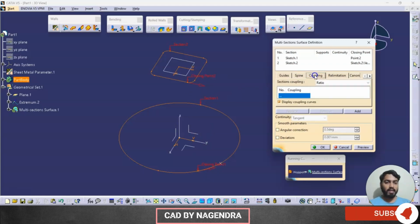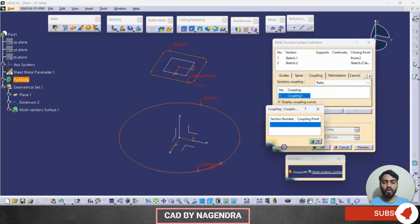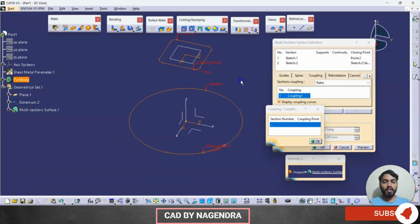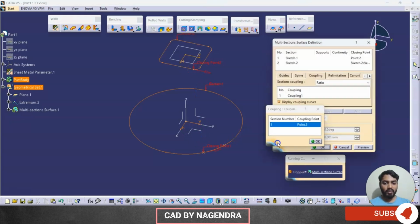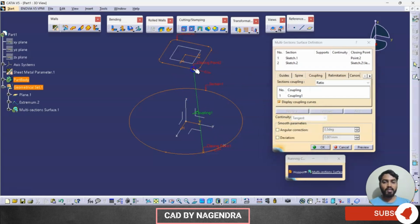Then we'll go here with coupling, add. To create a coupling we need 2 endpoints. On the rectangular profile we already have 8 points, but on the circle we don't have any points. So we need to create a coupling point: right click with the mouse, create point with reference to the existing closing point. Let me select this point and say OK. If you see, one point will be created exactly equal to that. Later you just select the existing point like this, and one coupling will be created.